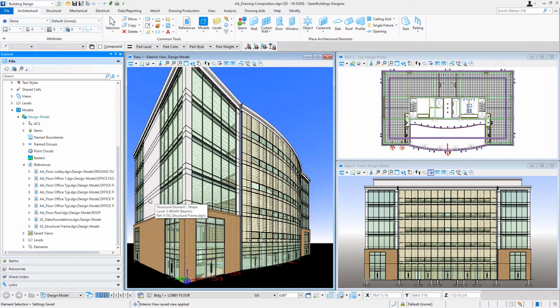So the curtain wall for that floor has been modeled once and is simply referenced multiple times to the building model. That means I only need to modify one floor and that would update all 4 floors. But even so, on that one floor, I have this corner panel which repeats at each corner. So I actually have 8 instances of that panel.